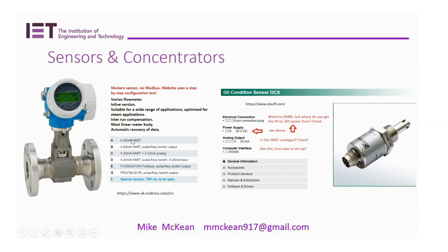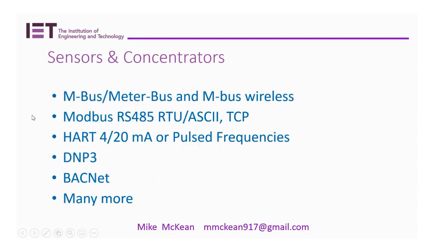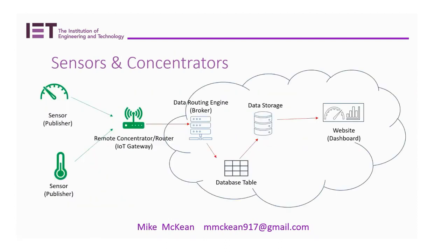Right. The important point I wanted to raise was, look, that says 4/20 milliamps, and that says 4/20 milliamps, but that says HART. That doesn't say HART. They might work. Just be really careful. Make sure you really check. And other things to check, you know, things like in the M-bus world, you get power, or you should get power from the gateway. So just to remind us all, in the M-bus world, the correct thing to do is get power from this gateway, not anywhere else.